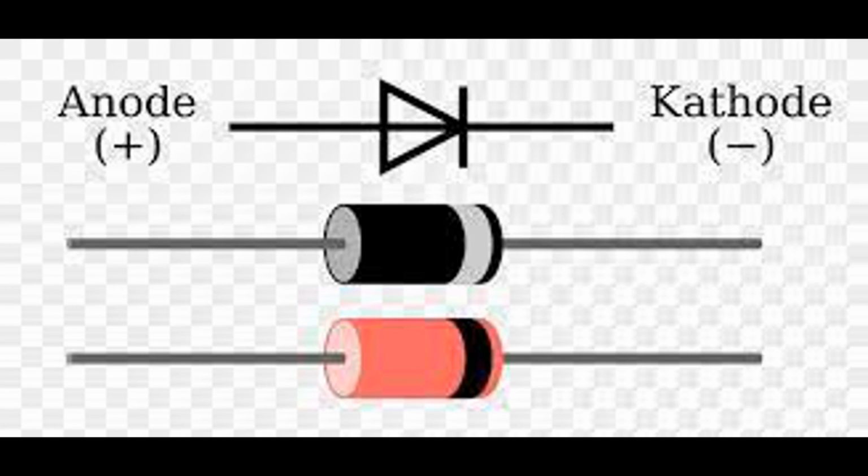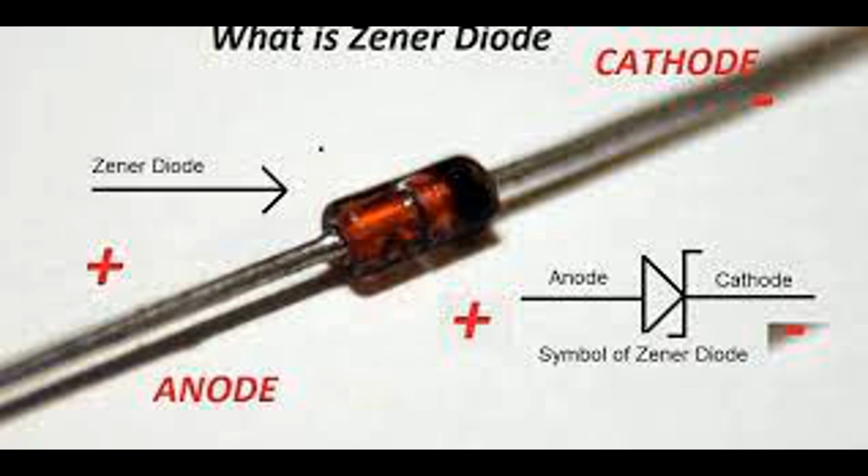The diode demodulator works by rectifying the AM signal to produce a waveform that follows the envelope of the carrier signal. This envelope waveform represents the variations in the original information signal. While diode-based envelope detectors are simple and effective for AM demodulation, they may introduce distortion and require additional filtering to improve signal quality in practical applications.